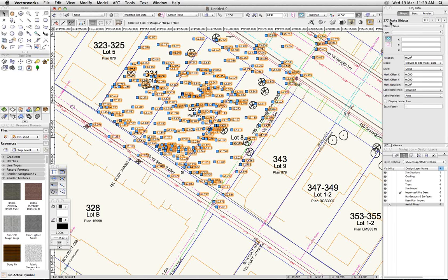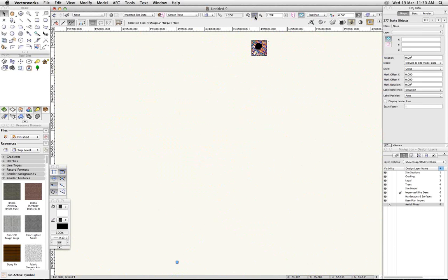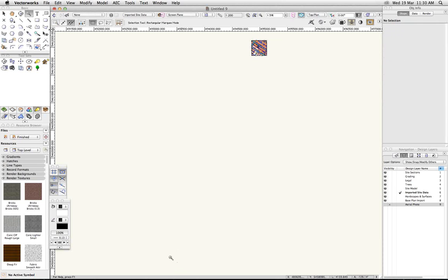I've got all of my stake objects. Before I do anything else, I am just going to click on Fit to Objects. And sure enough, there's a stray. There's something way off to the side. With both DWG and with these survey points, this is something to look out for. Look out for the stray objects out in space. In this case, I don't think it's an accident.